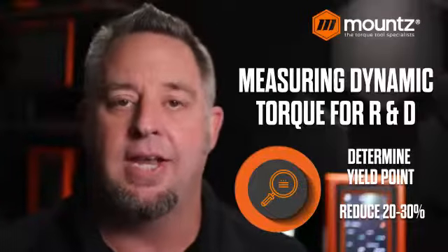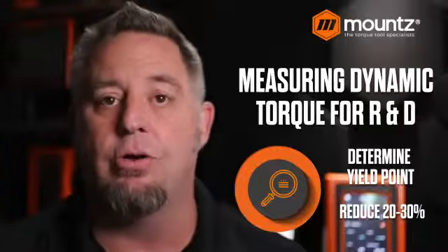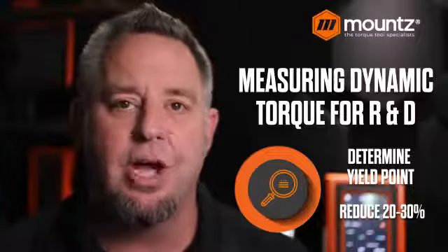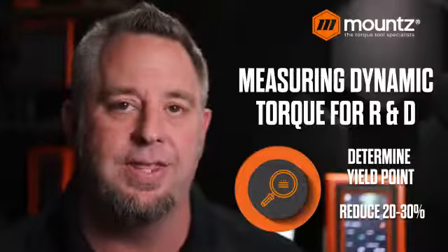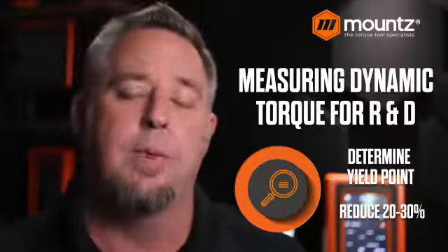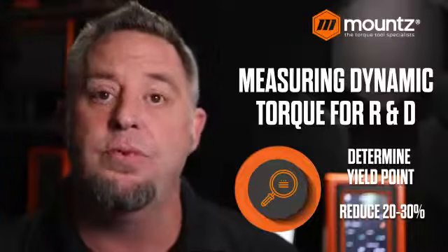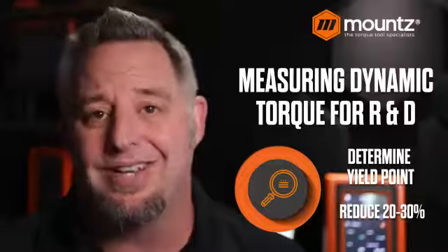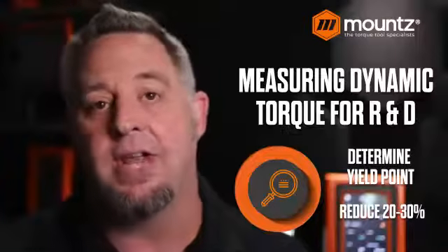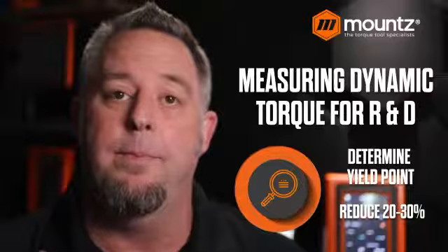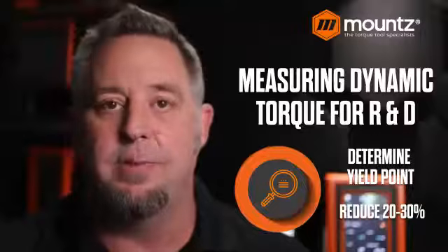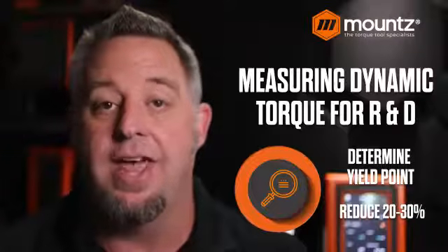And when we're looking at developing a torque specification, what you'll do primarily is take that to the yield point of the fastener. So at the point at which the fastener breaks, we can measure that particular torque value. You can do that in torque over angle. You can do it with torque over time. But this helps to develop the point at which the fastener moves from the elastic to a plastic state. And so if we can keep that clamp load for the fastener in the elastic state, that is going to be the best scenario for that particular fastener.